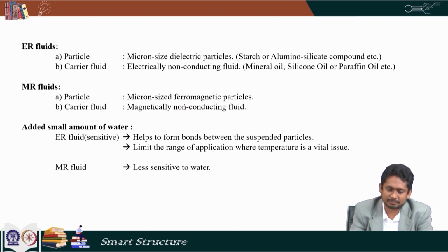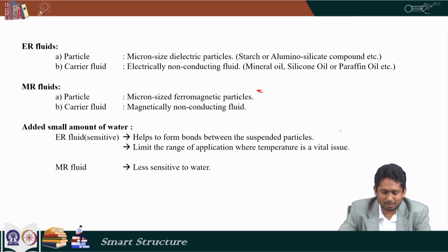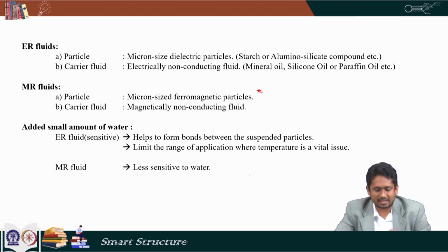In MR fluid, micron size ferromagnetic particles are used, and the carrier fluid is a magnetically non-conducting fluid. Now if a small amount of water is added, then in electro-rheological fluids there is a significant change, as bonds are created between the suspended particles, whereas MR fluid is relatively less sensitive to water.